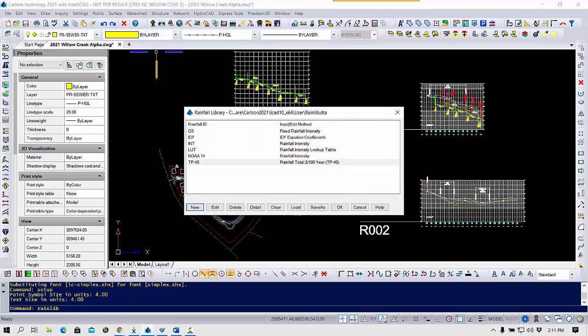Next, we would like to talk about Hydro 35 maps. The Hydro 35 method is used to define IDF curves for the central and eastern portions of the United States. It requires rainfall accumulations of 5, 15, 60 minute storm durations for the 2 and 100-year storms. You can select the map button to open the rainfall map and pick a state on the map to zoom into the state map, and then pick the location to get the rainfall depth.